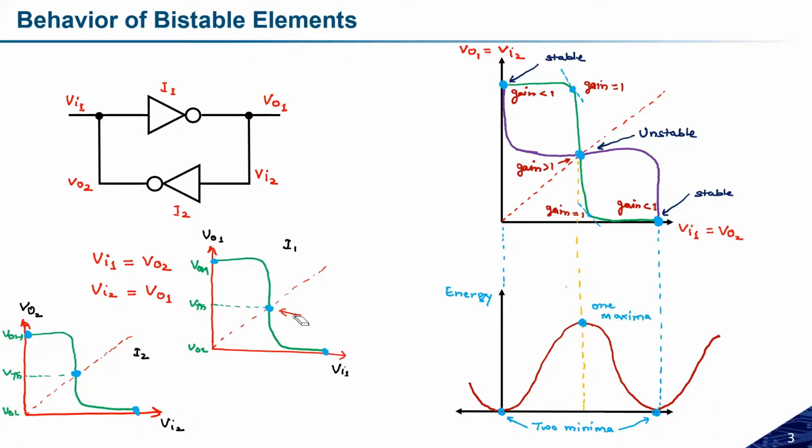Similarly, for the second inverter, if both the transistors are in the saturation region at this point, the output which we will observe will be equal to the threshold voltage of the inverter, or the threshold voltage of the circuit. We can also call this the switching voltage at which the transistors are switching.